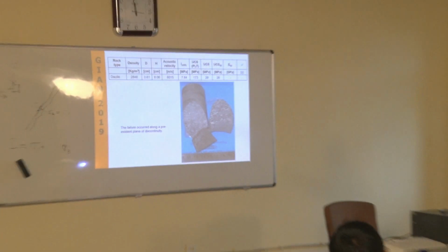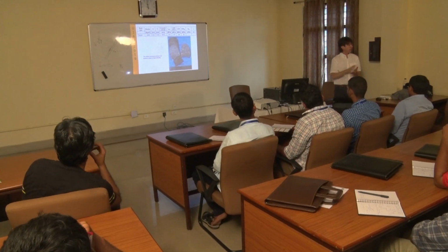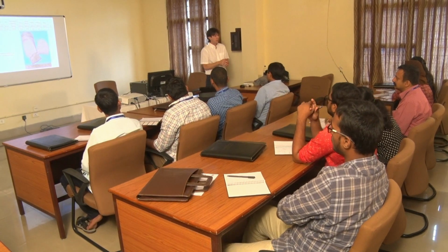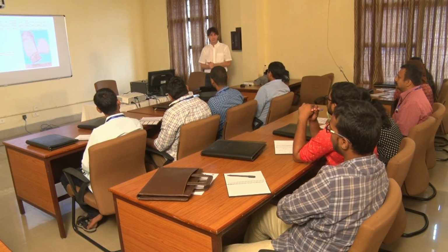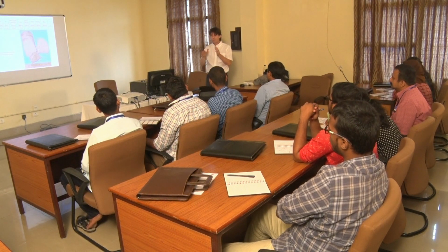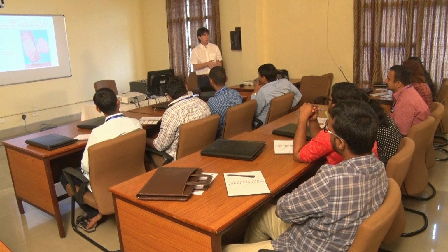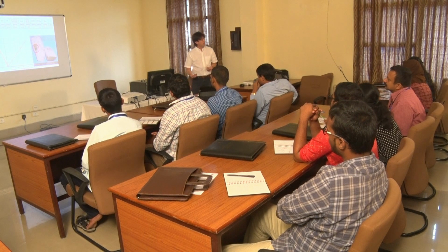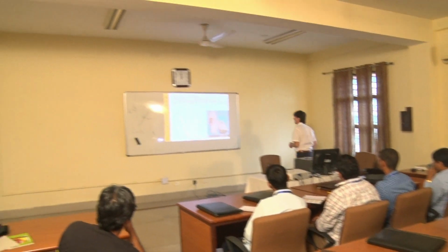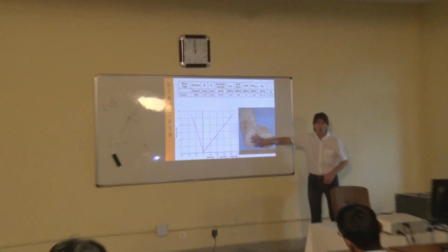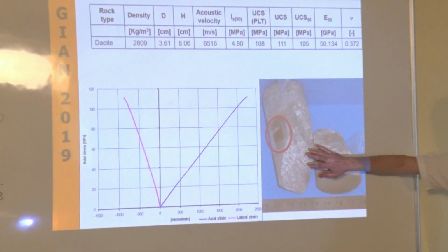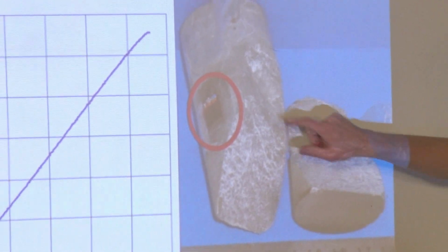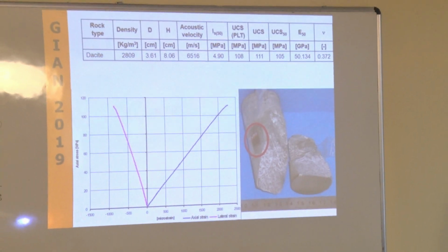Right? It's going to be very useful because it's telling you what that particular vein is made of, and what is the strength that you can actually get out of those fractures. But for the characterization of your material, nothing. And then this one, actually this one was positive. It's more positive because definitely this is a plane. And the color tells you that it was sort of filled. So this was a fracture that was already there. But this gray color is telling you that that was intact rock.